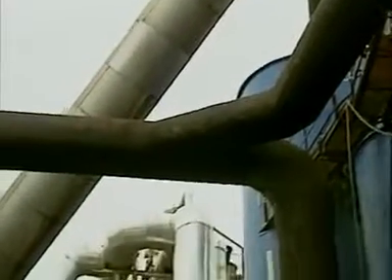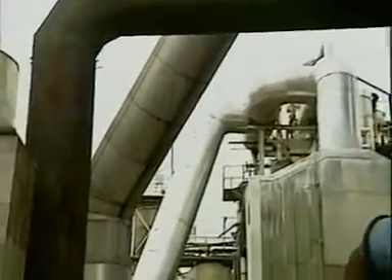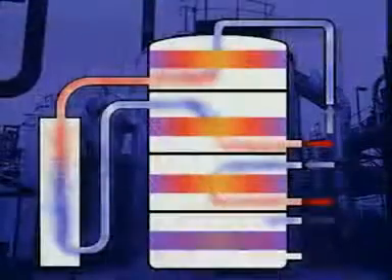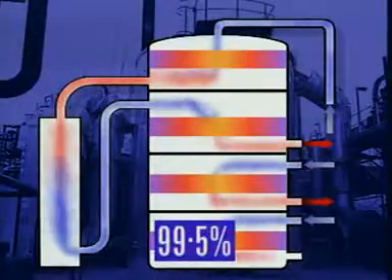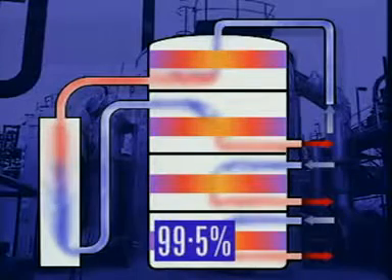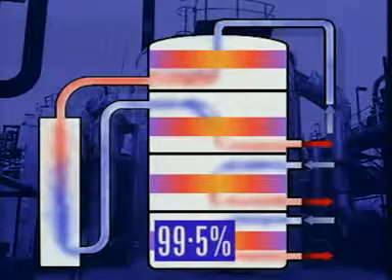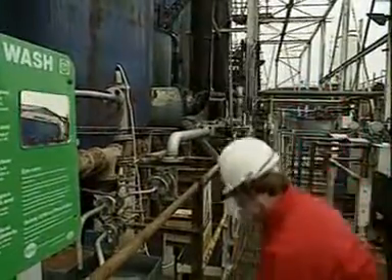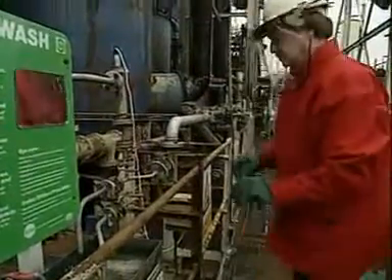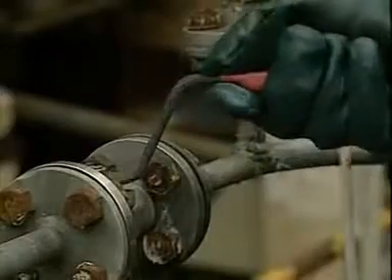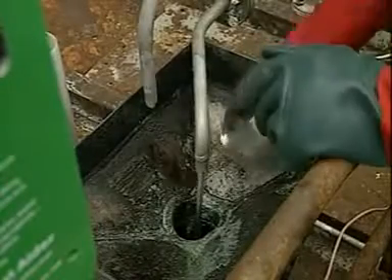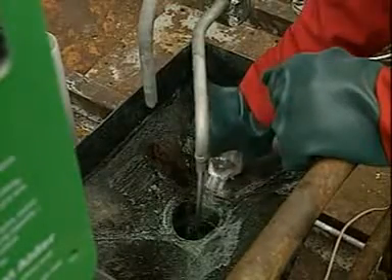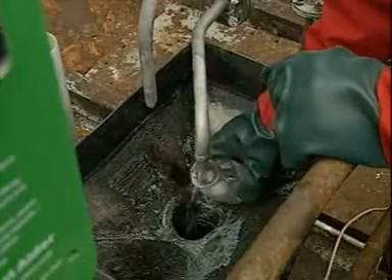The gas from the top of the tower still contains some sulfur dioxide and oxygen and is fed back into the final bed of the converter, after which 99.5% of the original sulfur dioxide has changed to sulfur trioxide. The 99% concentrated acid is diluted with water to about 98%, for example, and this increases the volume of the acid. This extra 1% or so is the volume of the acid that has been made.